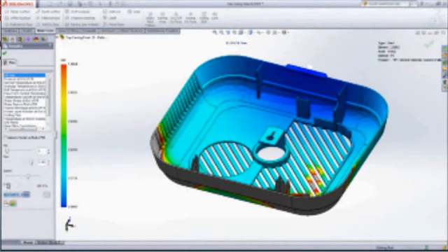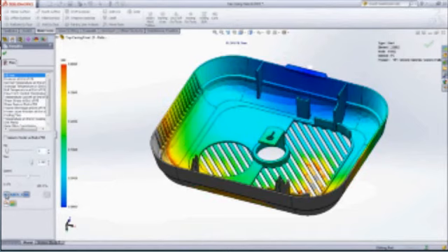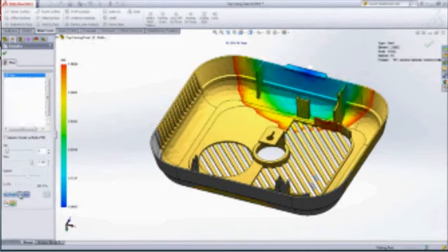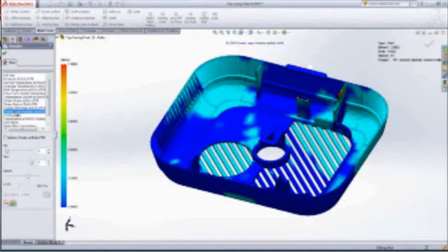Because we decreased the thickness too much, we created a short shot problem. No matter what you do, how you set up the machine, or how fast you inject the plastic, you just can't get the plastic to fill up 100% of this mold cavity. These molded parts will be nothing but defects.